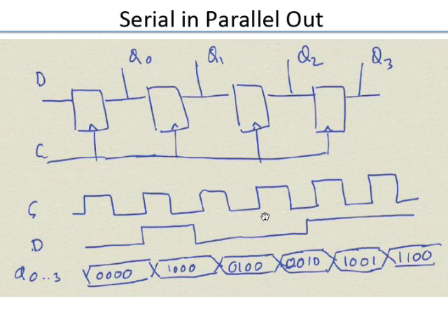So you have to spend extra time, as opposed to something, suppose you had a random access memory where you could randomly select one of these flip-flops and write a value, then you can do it in a single cycle. You give the address, you select, you write it, and you're done. Whereas here it takes more cycles to set up the pattern because you have to go one by one.